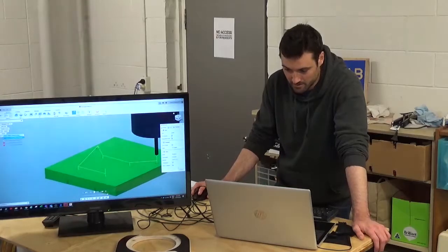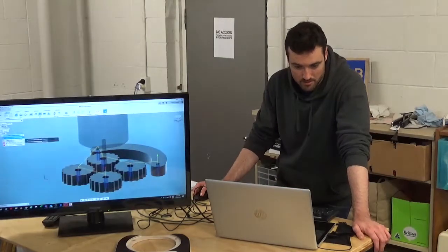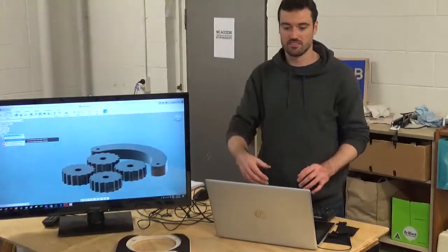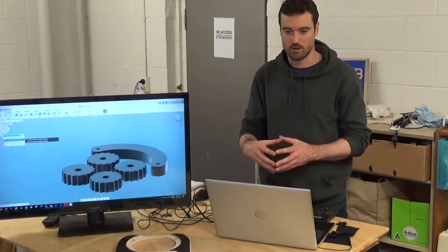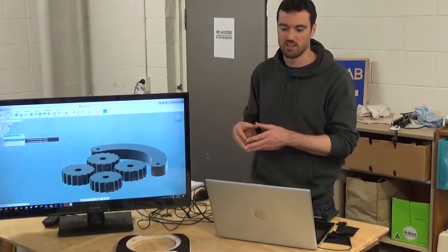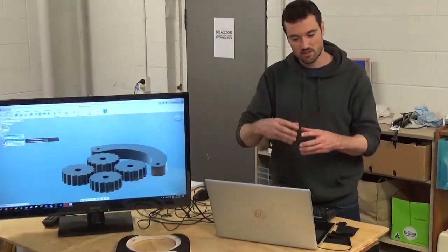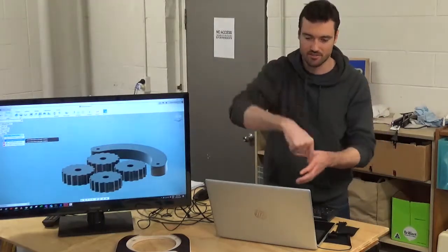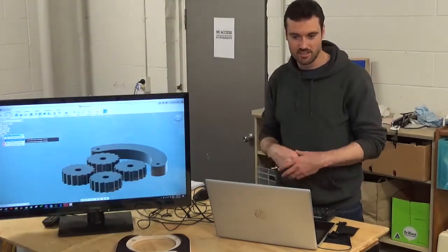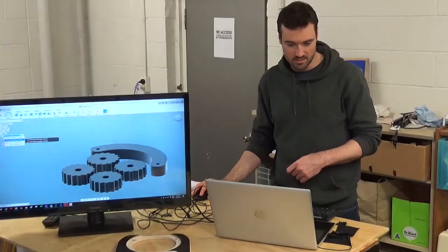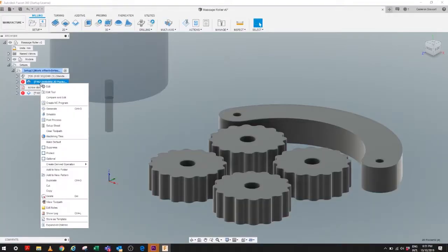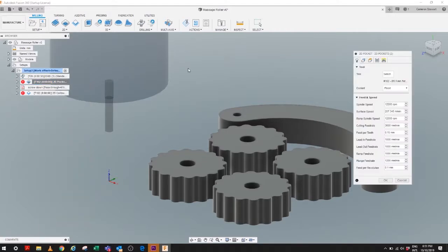Okay, cool. Next one. There's a thing here called screw down, which is basically passing an M code, like a macro, to the CNC machine. When it does this operation, the machine moves out of the way and allows you to screw your piece of material into the board. But we'll skip that, that's an aside. We'll leave that as a placeholder and have a discussion about that later. Next, we're going to do the pocket.